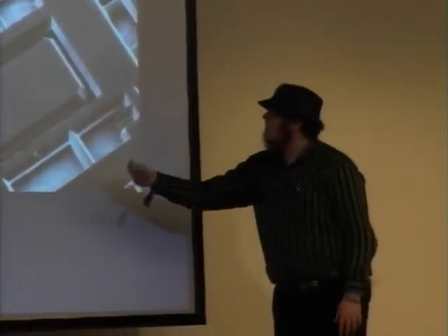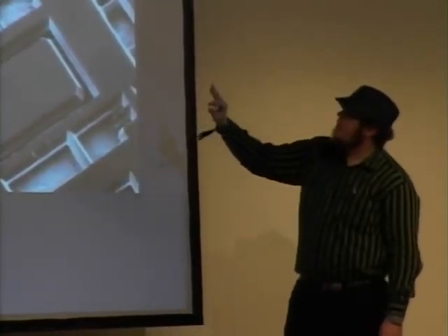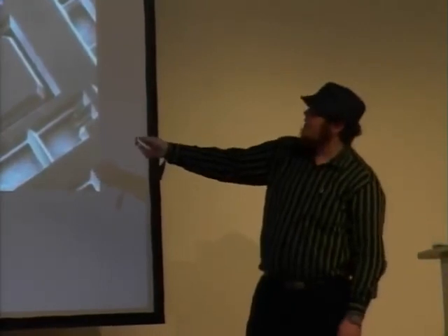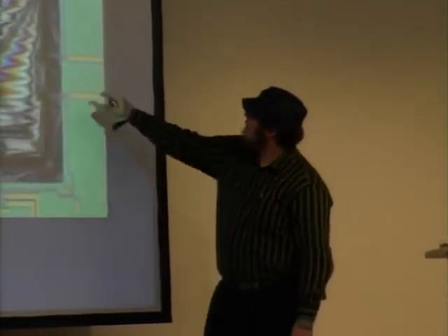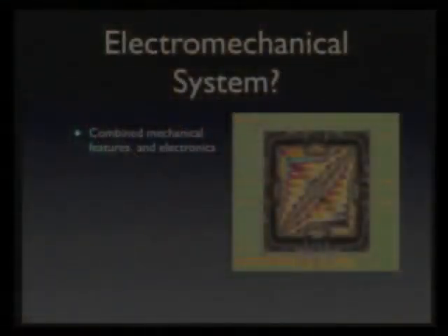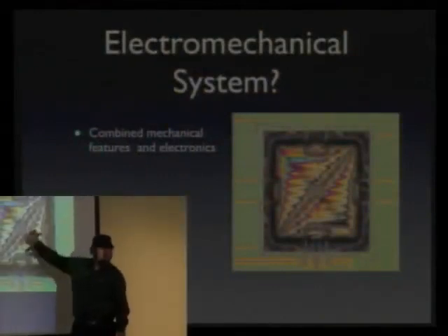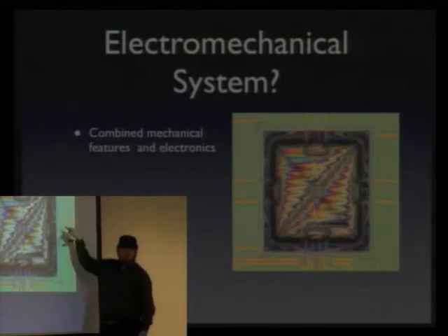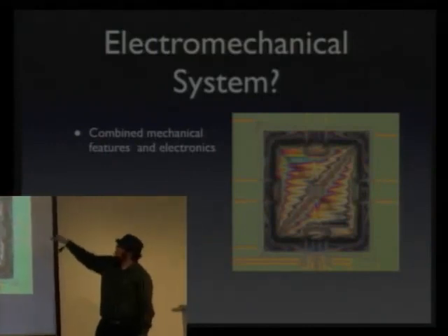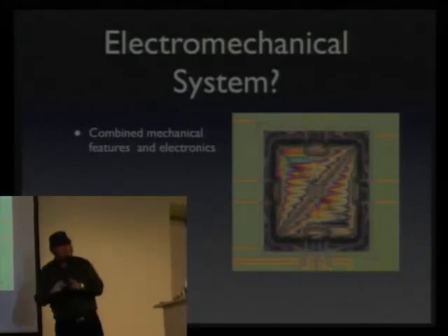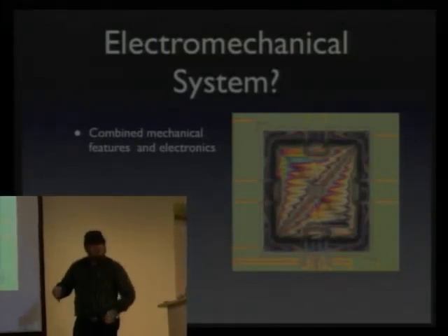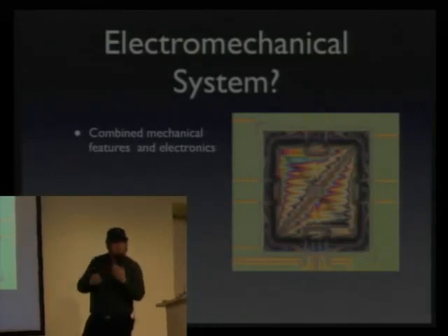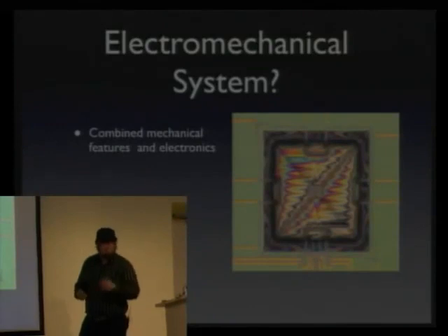But with this, you don't see any electromechanics. This is purely mechanical. What you can see here is a pressure sensor, with embedded measurement structures. This is a big membrane etched out of silicon, and here you have the sensors on the four edges of the membrane, which are connected with aluminum. So what you get is basically a Wheatstone bridge, where you can read out how much the membrane is moving.